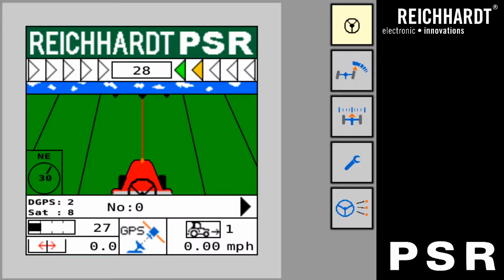There's a third state with our system. It would change the icon to a red indication. I'm going to go ahead and do that by stopping the GPS output to the system. And give it a few seconds. And now you see it turns to a red icon. And that means there's something preventing the auto steer from engaging. I'm going to go ahead and click on this, and this will actually give us an indication or an error code.